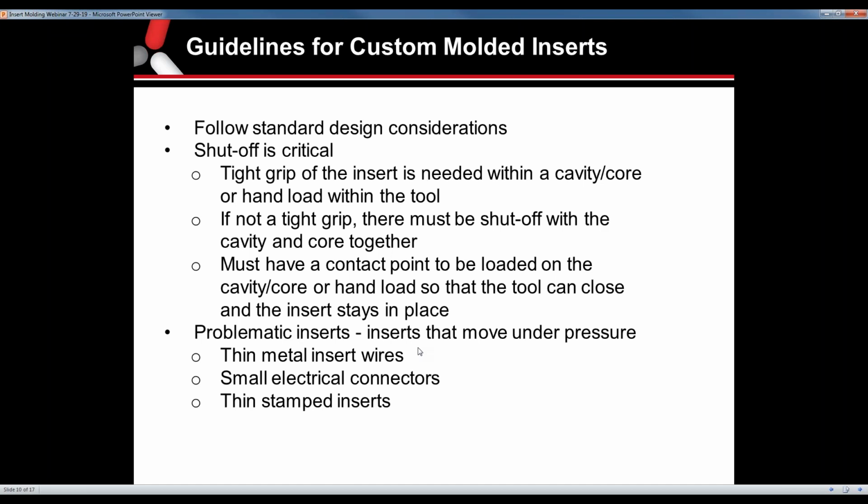So just be aware when you're designing your part to think about how it's going to be held in the tool, and where it is held in the tool. That shutoff is critical. And as Glenn said, we might be running into flashing issues with the material, or the insert floating or moving around in the tool and not being in the right spot.